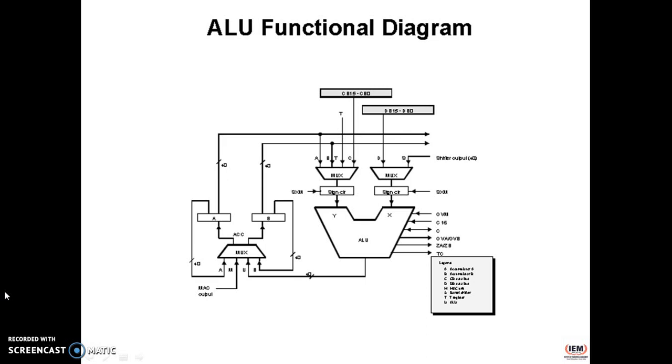Each accumulator is divided into 3 parts: the low order word, bits 0 to 15, the higher order word, that is bits 16 to 31, and the guard bits for the overflowing cases, bits 32 to 39.